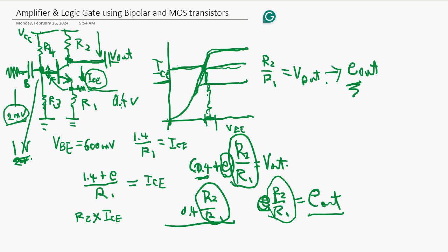However, this is like a low pass. Here's a low pass, and there is the capacitor on the transistor. This acts like a high pass. The collector node has a capacitor, so the frequency response is like a low pass. At a certain point this transistor starts amplifying, and the high pass effect comes out, giving a limited range of amplification in frequency, up to F2.